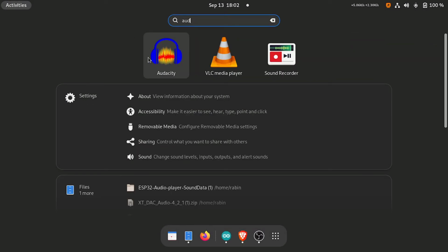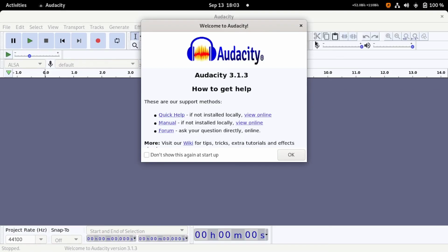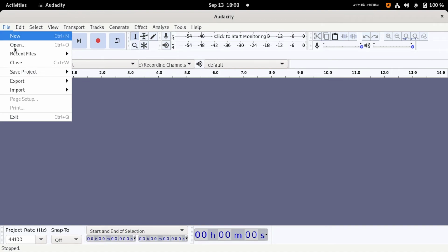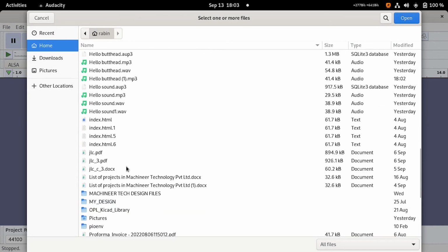We must keep in mind that ESP32 cannot play the audio file of .mp3 format. To play audio sounds on the ESP32 board, we need audio files in .wav format. After that, download and install any audio editor app. We have used Audacity in our case. This app will be used to change the file type, sample rate, and other properties.